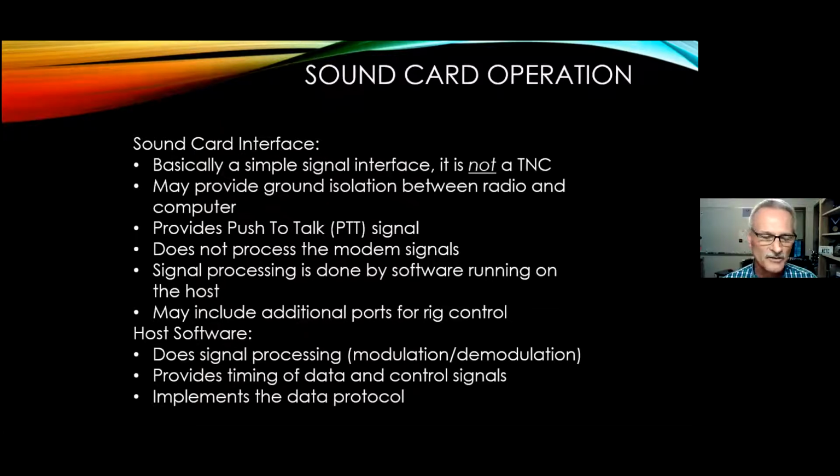So all of the signal processing is going to be done by the software that's running on the host computer, okay? And that software is going to do the modulation, demodulation, essentially. It's going to do the timing and the control signals like push to talk. And of course, it'll implement whatever the data protocol is that we happen to be utilizing.